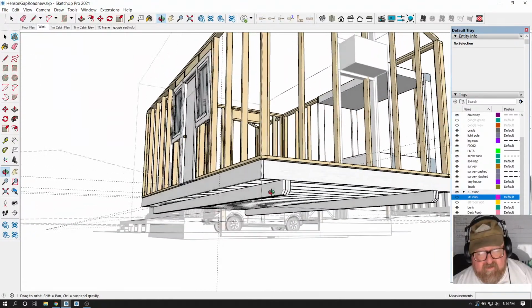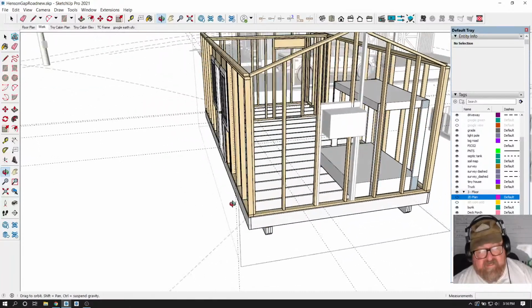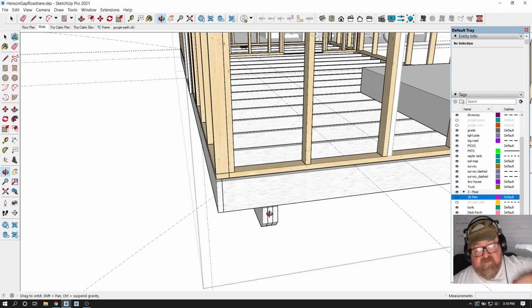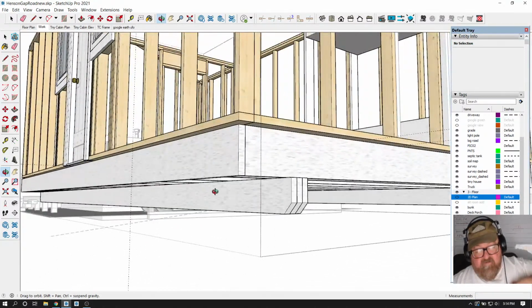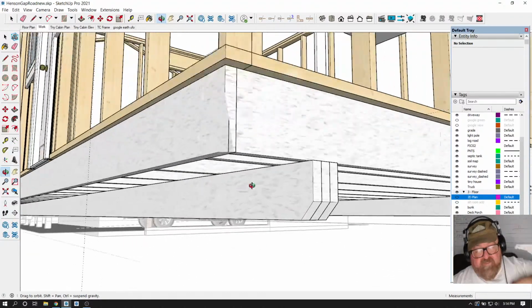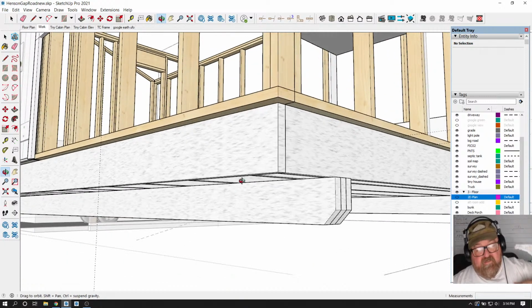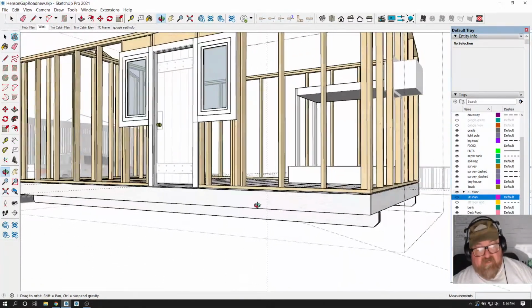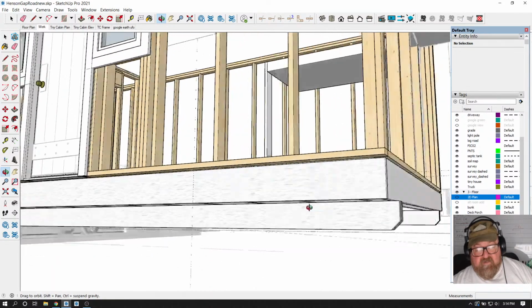If I could get 24-footers, I would, but that's going to be an expense and a headache I don't need. Since I'm making them 4.5 inches wide, I can just build it up and run lag bolts through it. I may use joist hangers, actually like rafter ties, to attach the joist, because if I ever pick this thing up, I don't want to rely on toenails from the joist to hold it on there.